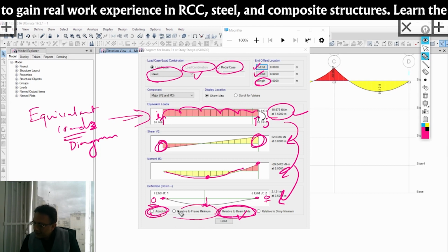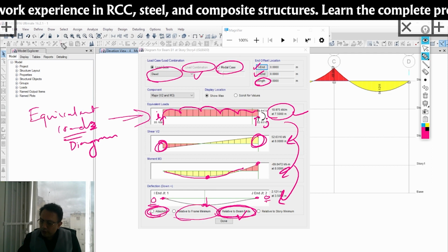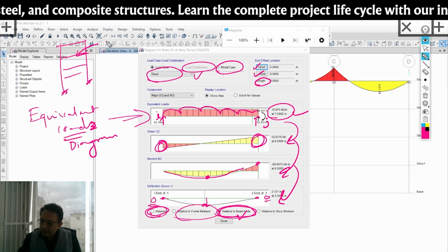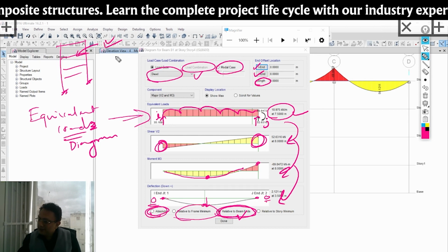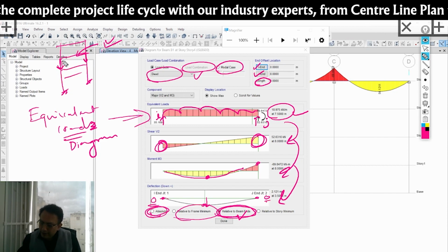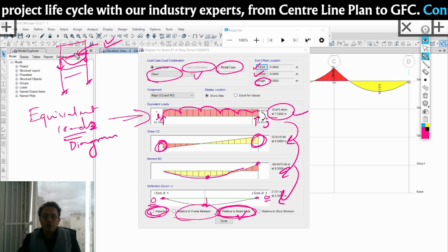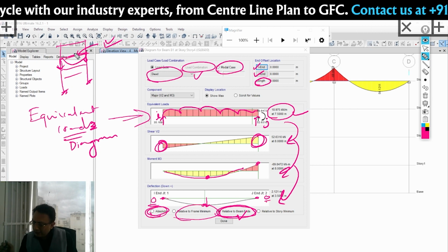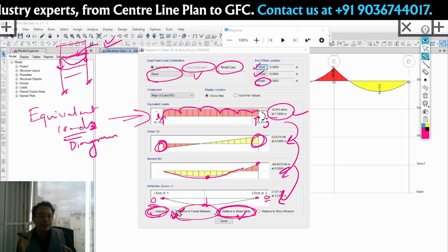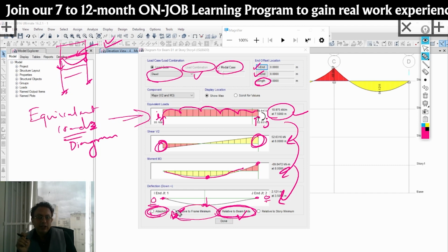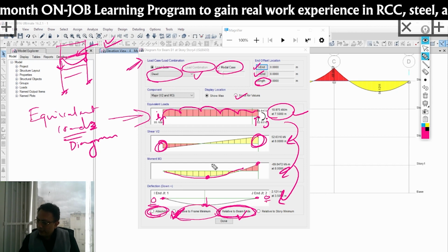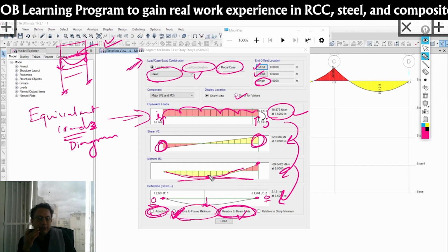Generally speaking, this is relative to the frame. You know that there is a portal frame analysis. So in the frame, if you right click this particular beam, then what happens? How much the frame is also going down, the actual shortening of this particular column. Pertaining to that, how much the beam is also going down over here. That will be shown if you click this option. Like that, many other options would be there. So what I'm requesting you is to go through such kind of options. You can scroll the mouse and check how much the bending moment is.